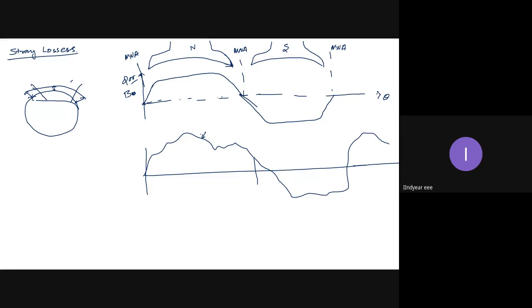If there are lower frequency components, then I should not worry, because losses will be reduced. So when I'm talking about the losses because of harmonics, it means it should be higher frequency components. I think this I have explained even in ECA once in one of the classes.